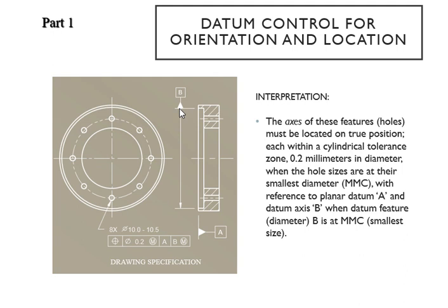So this one is just a dimension right there. Here is the plane of this right there. Okay, and then come back to this control frame, and you see the MMC right there. Since you're dealing with the MMC, you know that you have to get the smallest diameter. So the empty space has to be small in order for you to have the maximum material in your part, okay?